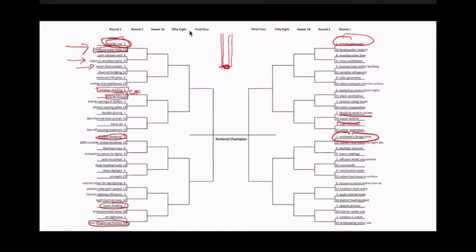One is air is a better conductor than argon. So if it's 0 degrees outside and it's 70 degrees inside, there'll be more convection going across that gap with air than argon, because argon just has properties that make it less efficient at transferring heat across, which is good. Less efficient in this case is good. We want it to be less efficient in transferring heat so it can be more efficient in insulating.